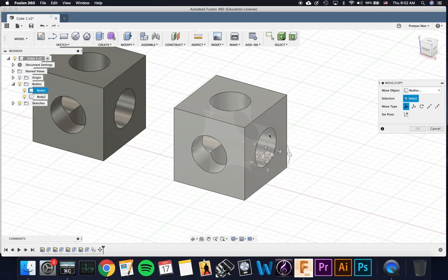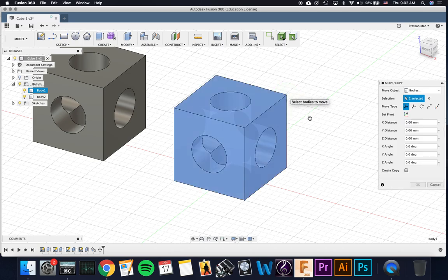And if you're on a rounded object, like look at this, the inside of this cylinder, you see how the move dialog box is angling itself? You don't want that. If you're doing a very complicated object that has no reference for its location, and if you know what I mean, you'll get it quite quick, this doesn't matter. But for right now, we're going to keep it on a squared plane with a y and an x-axis. We're not going to go in between with all these other options before. I want to just keep it on the y and x-axis, which means I want this move dialog box to be lined up, these arrows lined up with the proper axis.